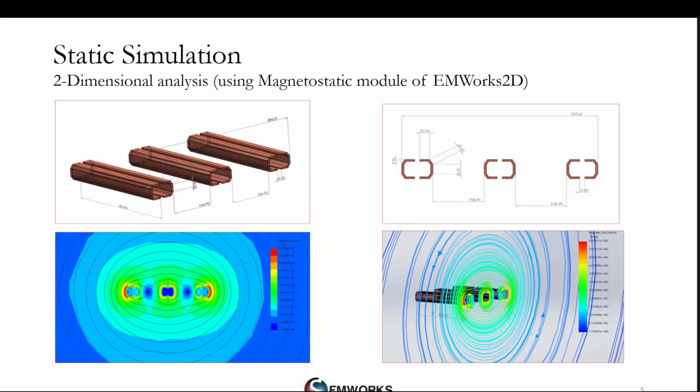As you can see at the bottom of the slide, two figures show the magnetic field results with the field lines superimposed. In this case, no shielding is applied, so the flux goes from one phase to another freely, which will increase the proximity effect in case of using AC currents. In the bottom right figure, we are plotting the field lines while we can see the 3D geometry.